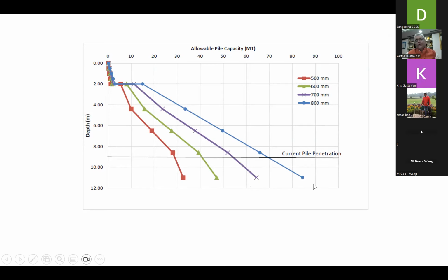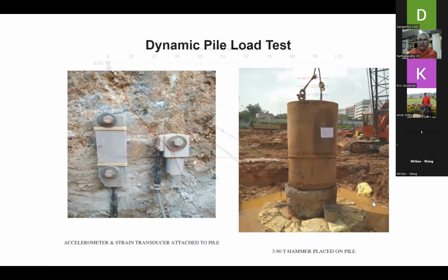Okay. So what do you do in such cases when the pile is already ready to put the pile cap? Some of them were already capped, but testing was not performed on all the piles, and some testing revealed the defect in the pile and also a very low load carrying capacity of the pile. So we have to remediate this further.